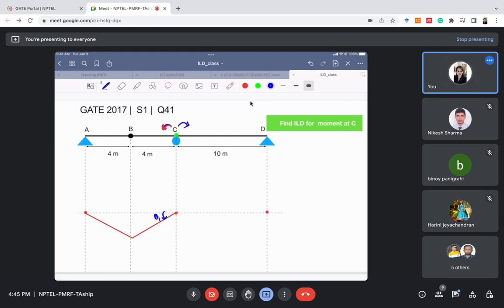how is it coming out? It is becoming like this, right? It is becoming curved. If I try to rotate it like this, because in this part A there's an internal hinge B in between, it was coming like this. But for part CD there is no internal hinge in between and I'm rotating in this way, but it has to be here also, so it is coming like this curved part.